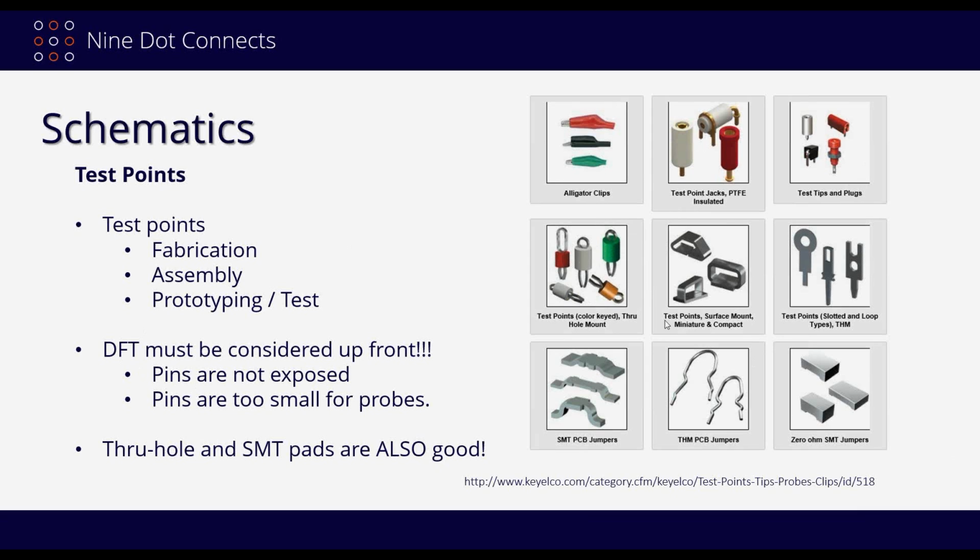And by the way, even if you don't have this, as long as you have a through hole and an SMT pad that's got the solder mask open so that you can actually get connectivity to it, that works great as well. Okay? The idea behind this is that if someone's got to put a probe on a fine pitch